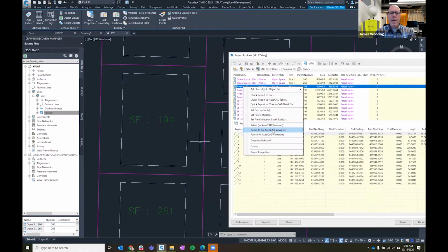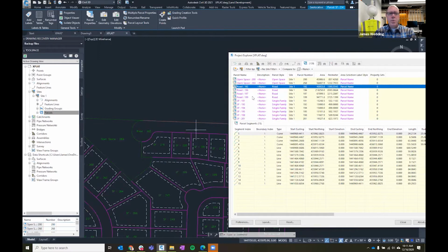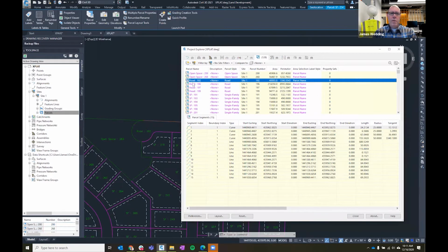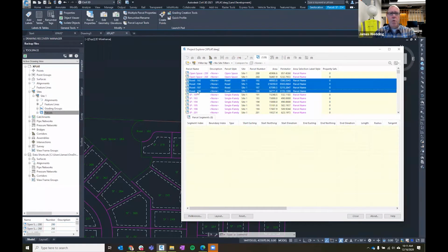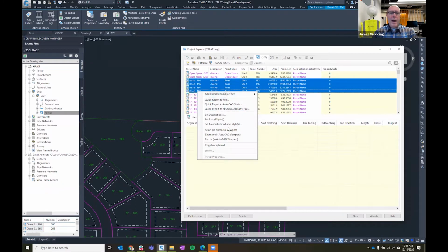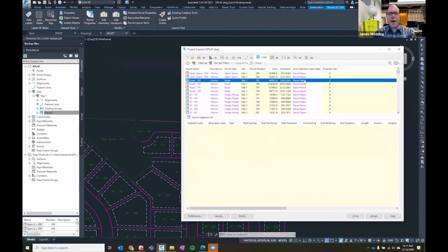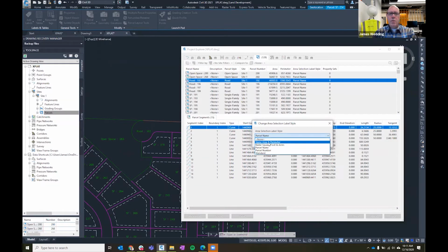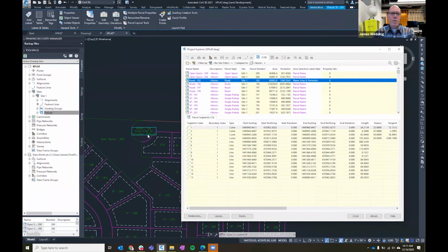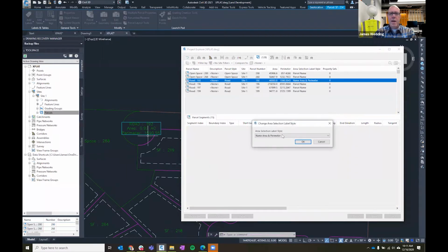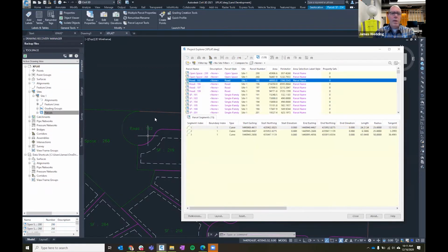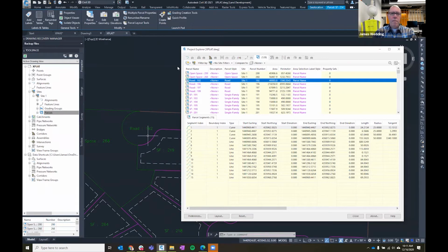Now, reviewing and editing, great. But I'm going to pan, and then we can also select multiple. When we pick parcels, let's just pick all 4 road parcels, we can edit, set description. We can do multiple things all at once really quickly. And anytime you see purple, you can double click that and you'll get some options there. So we can change that to name area, and you can see that it modified that one. That's not a great name or a great option, but you can quickly and easily modify all of those different pieces.